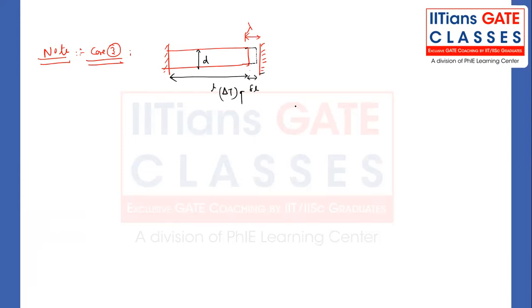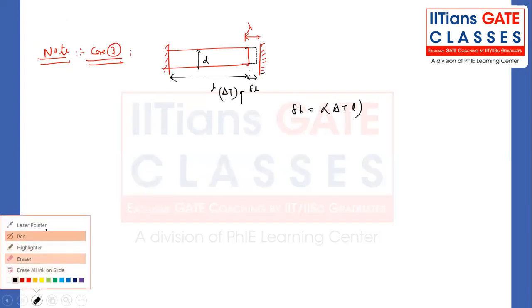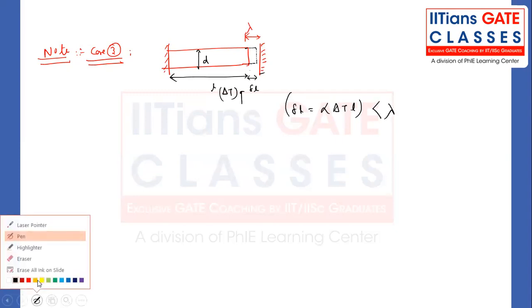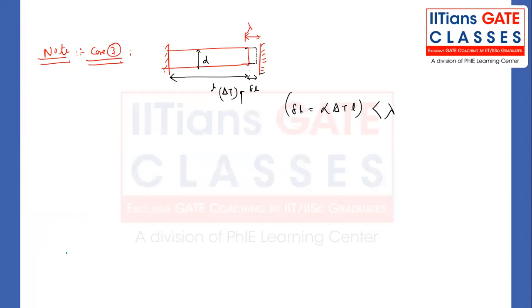This delta L is alpha into delta T into L. If it is less than lambda, there will not be any thermal stress. The thermal stress will be 0.